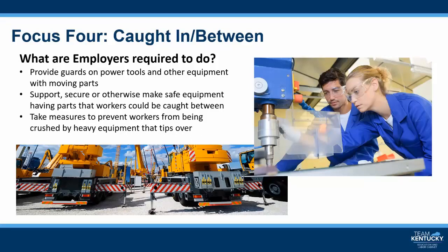This is to identify working conditions that are hazardous to workers, including ensuring that the support surface is firm and able to support the load. The employer must make sure that the material handling equipment is equipped with rollover protective structures. OSHA standards require that motor vehicles, forklifts, and earth-moving equipment must be equipped with seat belts. Employers must require the use of seat belts.